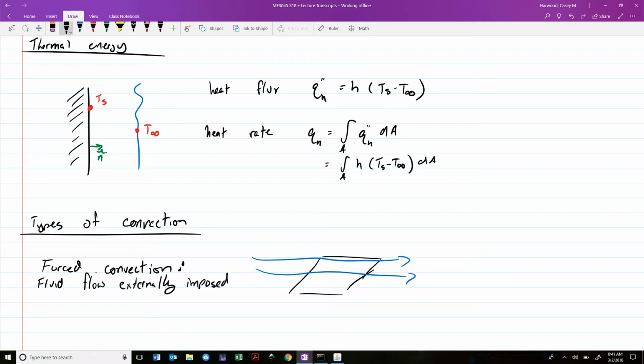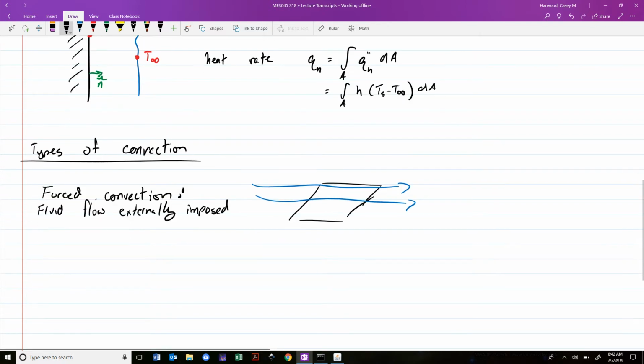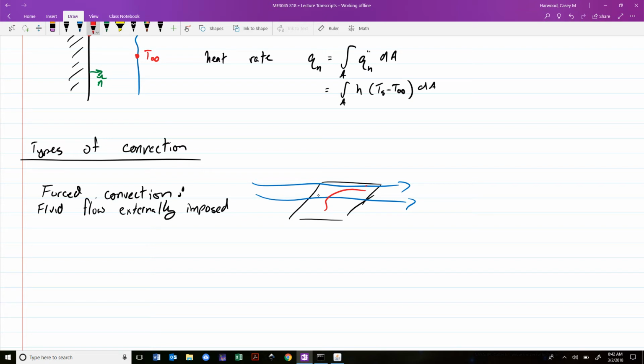That is, either the flow is moving because it's being driven by some upstream pressure, like a current, if you were to stick something hot into a moving body of water, that would be considered forced convection because the pressure field upstream is driving the flow. Other examples include fans, pumps, right? Generally, most of the things we think of as active cooling systems. Your laptop fan kicks on. What it's doing is it's moving over to a forced convection regime. So with forced convection, right, the idea is heat that's coming off of the object is going to be transported away from the object very quickly.